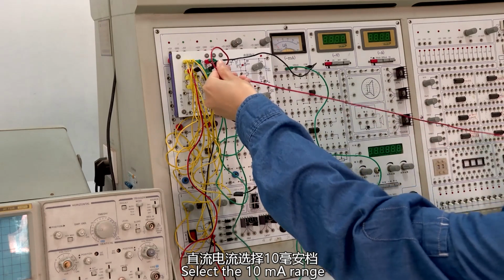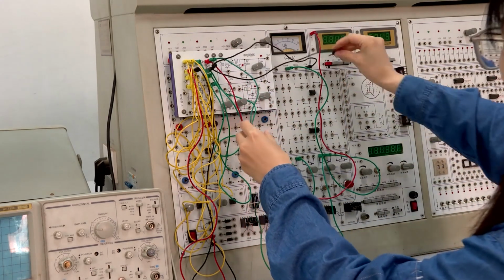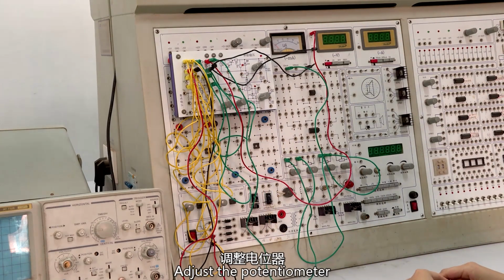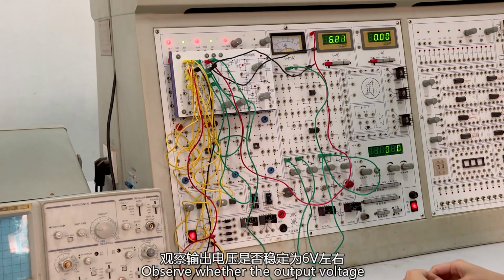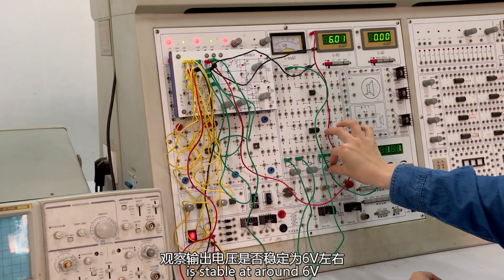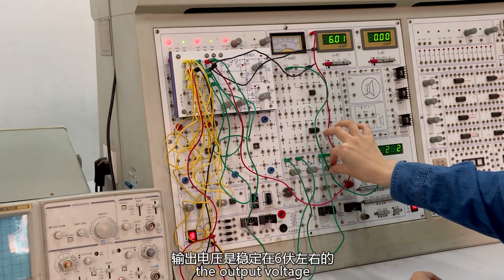Select the 10 mA range for the direct current. Adjust the potentiometer. Observe whether the output voltage is stable at around 6 volts. You can see that with the change in output current, the output voltage remains stable at around 6 volts.